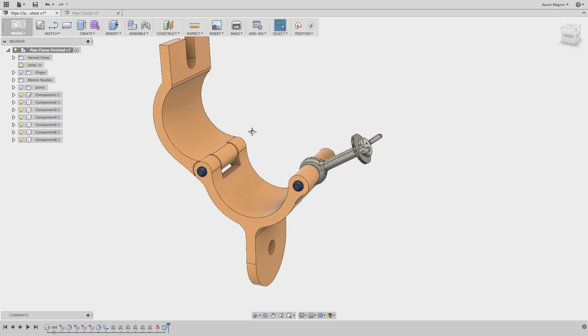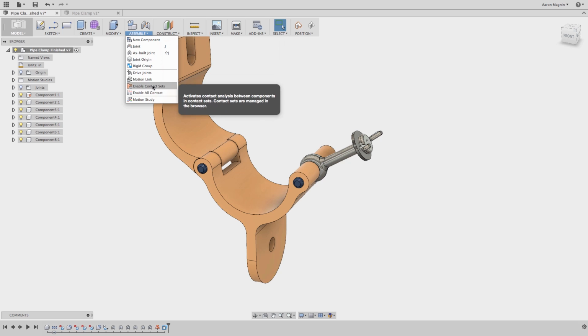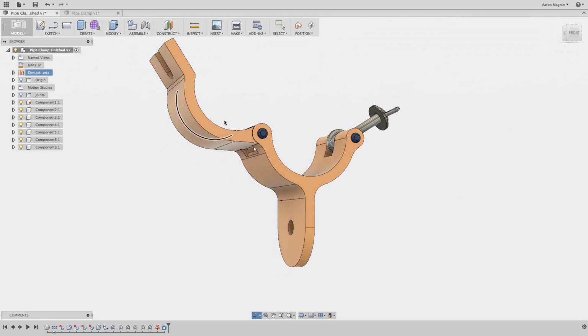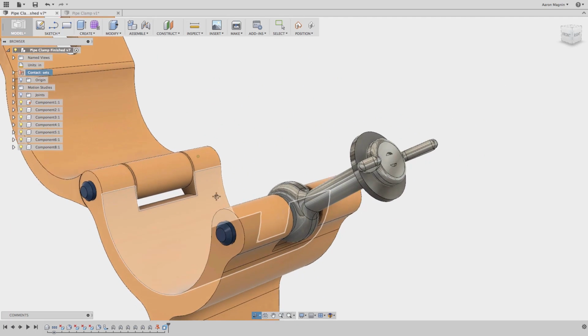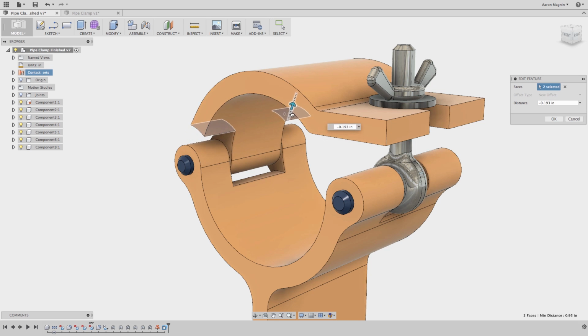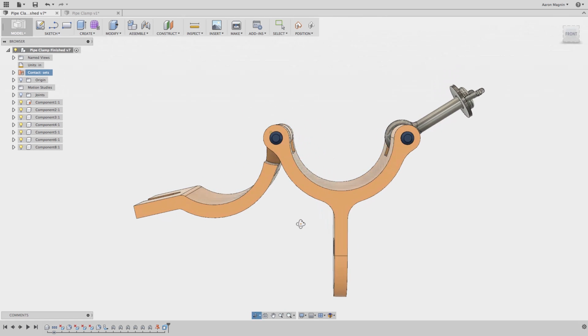By building these designs within this 3D environment, you can learn quite a lot about them as you're building or designing them. One thing that I like to show here is that you can do some things to understand how well it's going to work. If I do something here, I can enable contact sets and then add a contact set between, say, this part and this part. Once I do that, when I slide this, you'll see it's actually going to bottom out. It's going to hit the edge of this because I built that up a little too tight. One thing I can do to fix that is edit this offset feature that I've created here. So I can slide this up and build up a little space there. And just like that, I can jump back into sliding that, and then continue to drag it till it hits again.